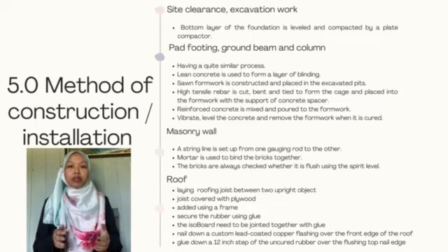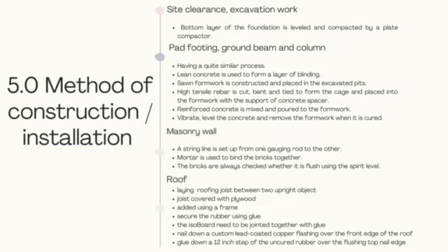Next, both must be covered with adhesive. At any inside vertical corners, cut and overlap the EPDM rubber, and then use the rubber adhesive to glue it down tightly. Nail down a custom lead coated copper flashing over the front edge of the roof, and as the last step, glue down a 12-inch strip of uncured rubber over the flashing top nail edge.